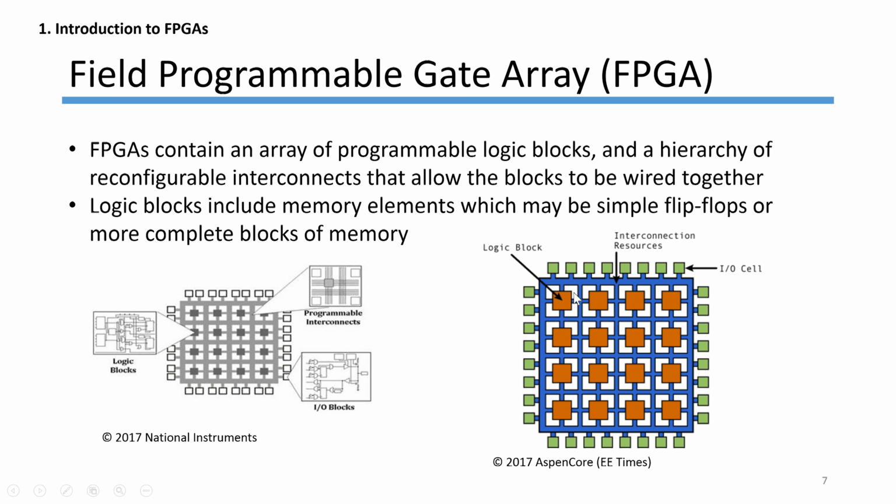And these all interface with whatever hardware you have through these input-output cells. Now, each one of these logic blocks includes memory elements, which may be as simple as flip-flops, or even just your basic programmable logic circuits, or it consists of more complete blocks of memory.